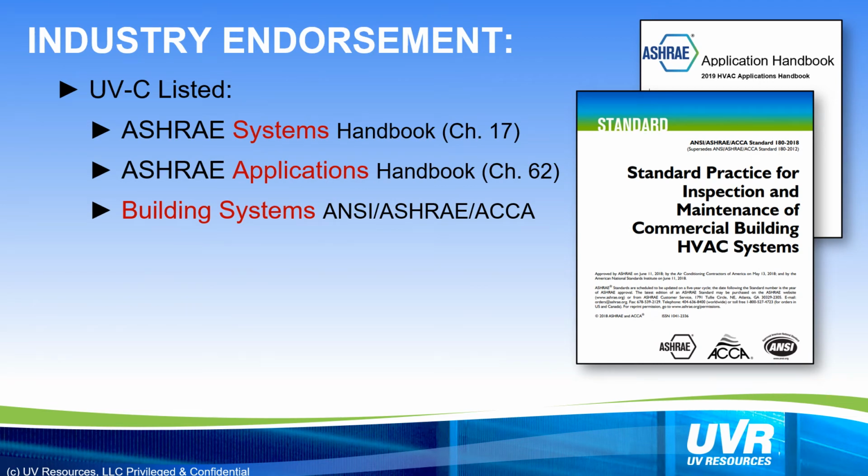UVC's germicidal effects are well proven in research dating back nearly a century. Many government agencies and professional associations offer guidance on the germicidal wavelength, including ASHRAE's 2020 Systems Handbook, its 2019 Application Handbook, and the current 2018 ANSI, ASHRAE, and ACA Standard 180 for building systems. This latter standard establishes minimum HVAC requirements for acceptable comfort levels, energy efficiency, and indoor air quality standards in commercial buildings.